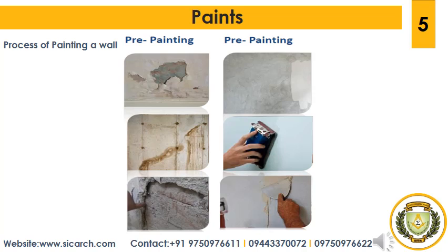and the pigment occurs. The procedure for preparing paint from stiff paints is: sufficient stiff paint is taken in a pot, and the remaining stiff paint is to be covered with a layer of linseed oil. The linseed oil, which may be either raw, boiled or pale, is then mixed with the stiff paint by a stick. The other ingredients of the paint are added. If a color is required, suitable pigment is added and thoroughly mixed.